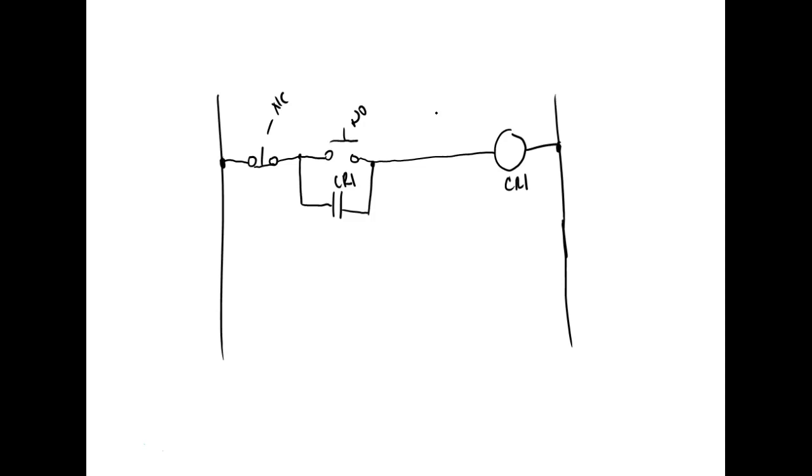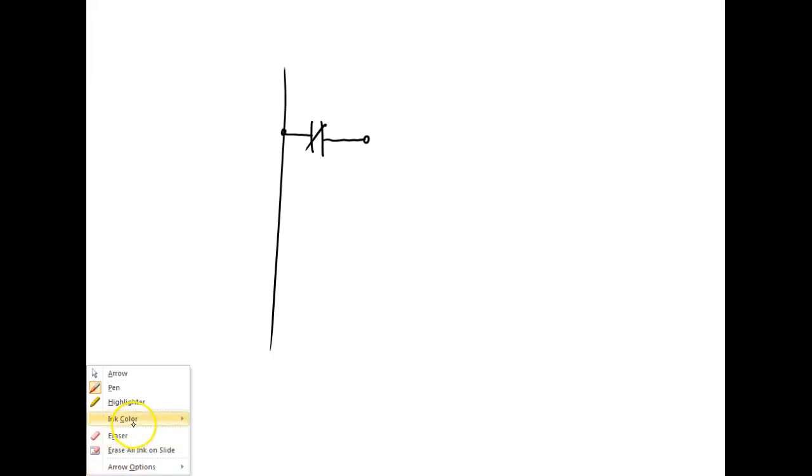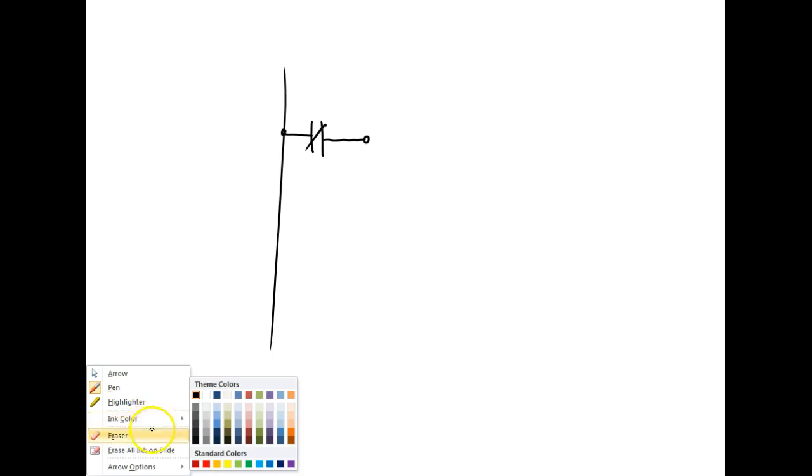You understand? So this gets people. If I was going to do this same thing in the PLC, normally we'd say, okay, I'm going to program this in the PLC. I come up here, I use a contact, right? You understand? Now, what would be the problem with using that symbol right there? Well, no, it's not normally closed. In PLC, we don't call that normally closed. We call it examine if open.